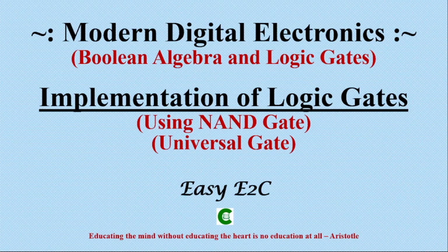So let's get started. First, we will implement the simplest gate, NOT gate, by using NAND gate. By now, we already have the understanding of the symbols of all the basic gates. Now, this is a symbol of NAND gate, or rather we can say this is a symbol of two input NAND gate. Here, both the inputs are shorted. So if we apply input A here, this is our boolean variable. Since these two inputs are shorted, the second input of this two input NAND gate will also be A.